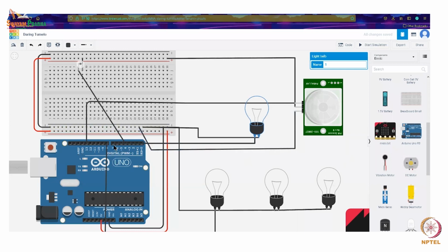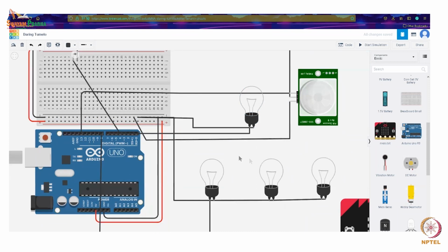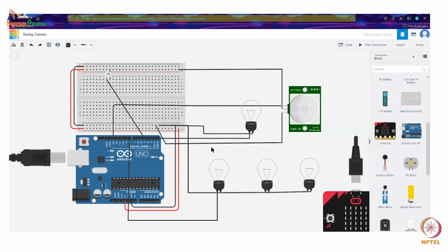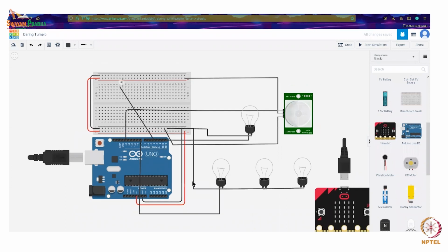We are connecting directly to the digital pins, but we have something called an actuator module. We have actuating devices which take the Arduino's simple 5 volt, 20 milliamp power and convert that into the 220-volt kind of supply. So we'll have an actuating module in between. But overall, the inputs and outputs are the things that you see here.